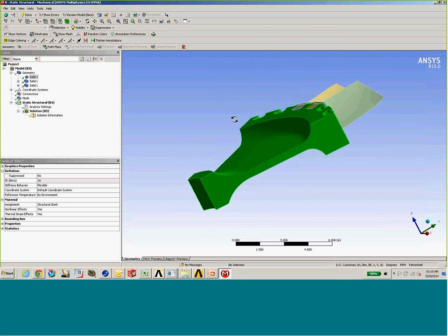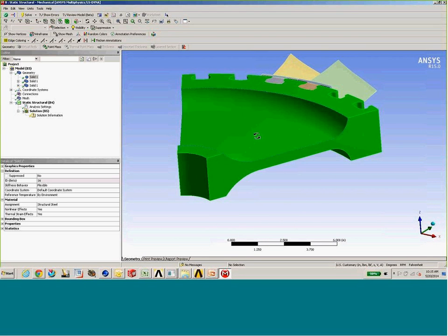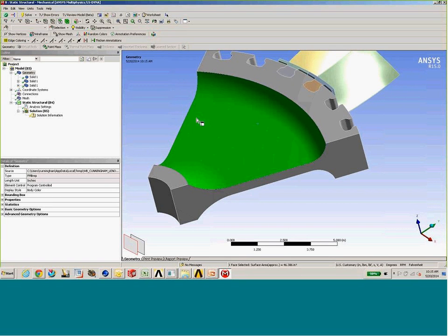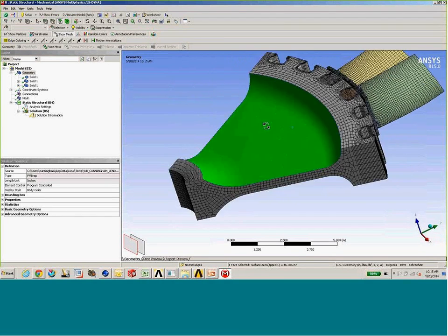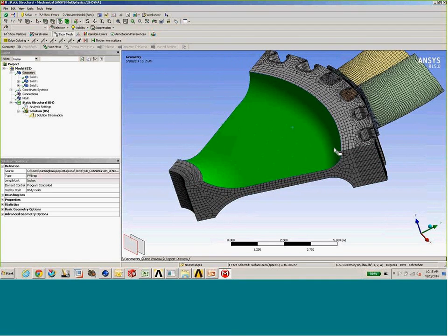But one thing that's kind of interesting here: normally you would expect to see multiple surfaces in terms of line segments, say on the curved surface here. You may see a division of the rotor at the end of the fillet radii. We don't actually have that here. If we click on the surfaces that were constructed from the finite element mesh, let's turn on the mesh to show that, you can see that we have one continuous surface along that face. Because again, what it's doing is using a fairly liberal concatenation tolerance to take the surfaces from the finite element faces and construct from it one large surface in this case.